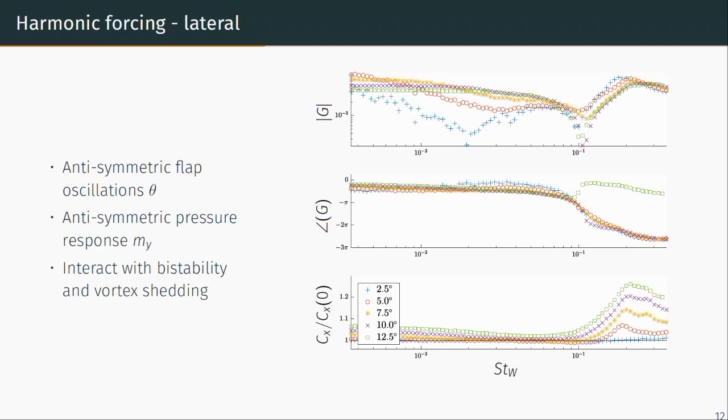And then as you increase the frequency, this response dies off somewhat. Until then at higher frequencies again, at Strouhal 0.2, you have again a large response. In this case, the flaps are exciting the oscillatory vortex shedding of the flow. They're exciting that particular feature.